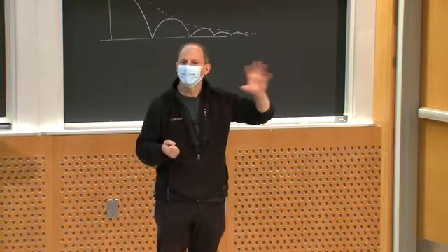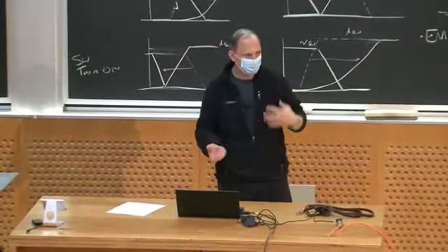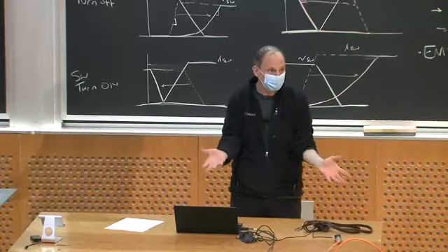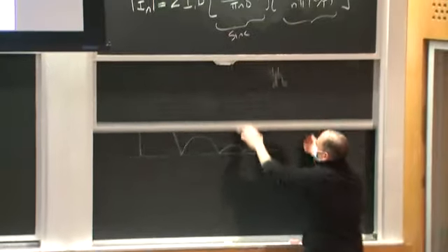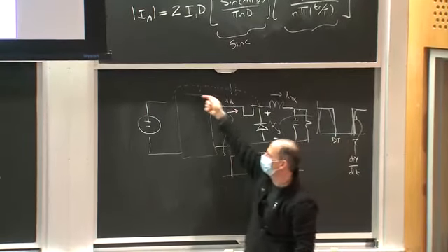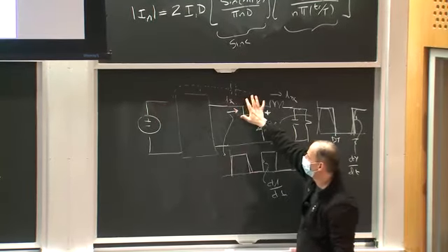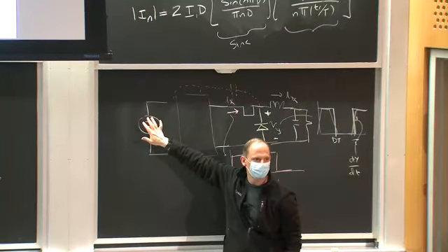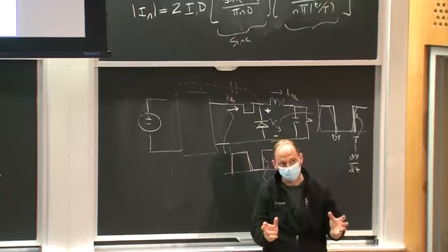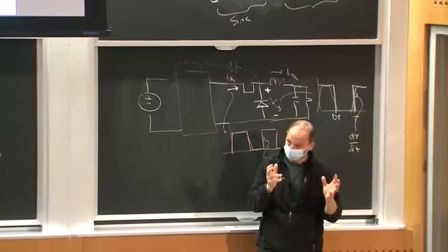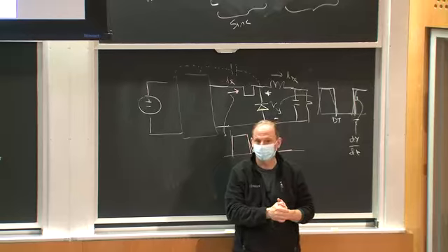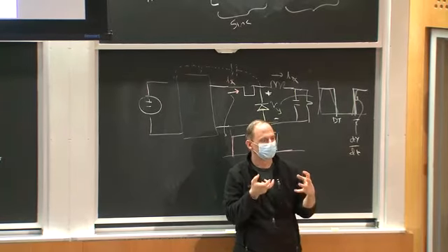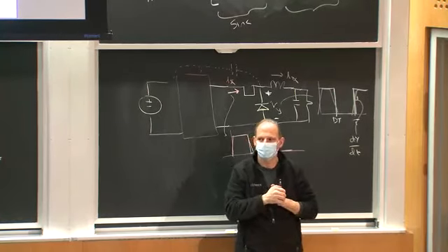So you might argue that the best way to get rid of the high frequency noise is, instead of generating and filtering it, just don't generate it. The stuff that's most likely to couple through, say, a parasitic capacitance is the highest frequencies. So if you just never generate them, it's a lot easier to filter them, okay? So you might not design your whole converter around this thought, but it really does help you with reduced filter size. And we've seen that with soft switch converters, you can often really make your filtering job easier.